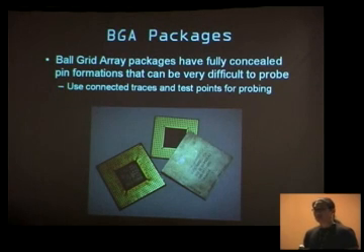How do you remove BGAs usually? Typically, if I want to pull off a BGA, I get a heat gun, and I just kind of point at it until you kind of see it. What happens is you heat it up, you see it shift slightly as the solder lets go, and the thermal stresses activate it. At that point, you just take a pair of tweezers and pull it off, and I take some solder braid and clean up the board. That's destructive. If you want to reball them, there's 10 guys in San Diego who you just give a BGA and they'll reball it for like $50 and put it right back on again.